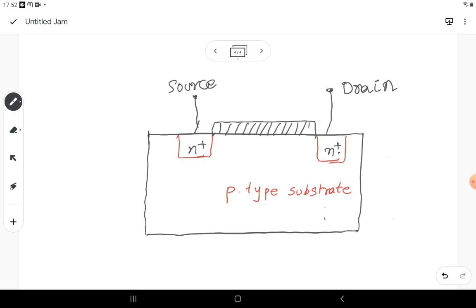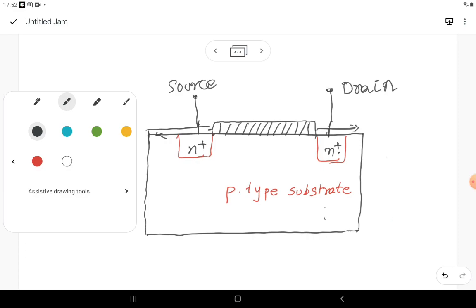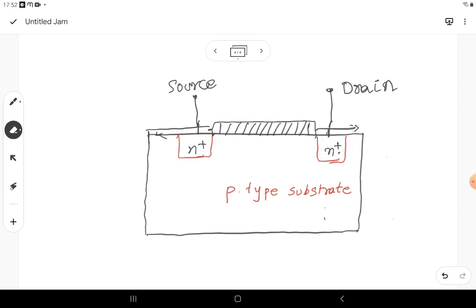So actually this silicon oxide layer will be present from this region to this region, and by using some different methods we are going to remove that silicon oxide layer totally. But as of now I am not including those things here. I am directly writing that the silicon oxide layer is going to be present between the source and drain region. But for the top of the entire substrate, the silicon oxide layer will be there. Later, due to some techniques, we are going to remove this entire material, and keep it only in between the source and drain regions like this.